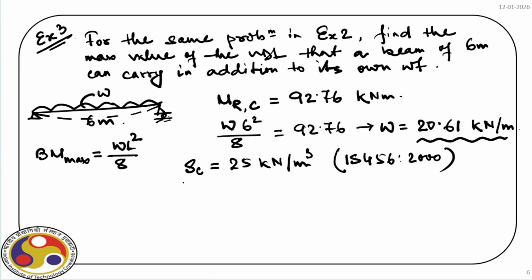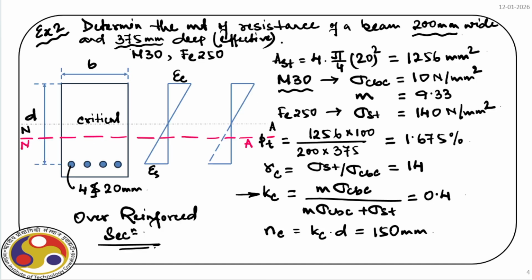So we can find out omega dead load, and that is nothing but cross section 0.2 times, we have the depth is 375, and we have to design the steel. If we see, we have 25 dia, so this diameter of the steel is 25, and if we have, say, a clear cover of 40 millimeter, so clear cover is 40 millimeter.